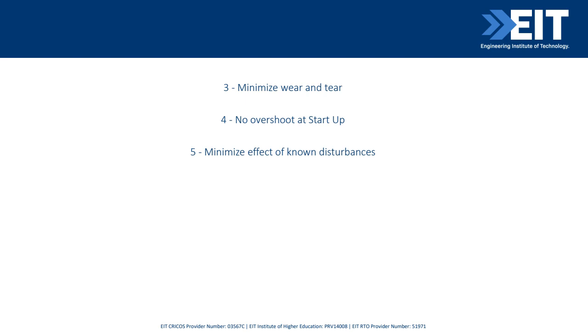It's generally referring to situations where you've got a valve. Yep, that's right. Thanks. Brilliant. So typically, when you look at a valve, oh, we've got a huge number of comments. Thank you very much. You people are all teaching all your chums here. Fantastic. Wear and tear for the valve. If the valve is not settling down, the control is reducing wear and tear to make operations smooth. Absolutely right. So a valve, for example, if we're trying to target a value and we keep tweaking the valve from 52%, 51, 52.5, bingo, bingo, bingo, it's obviously not a good thing.